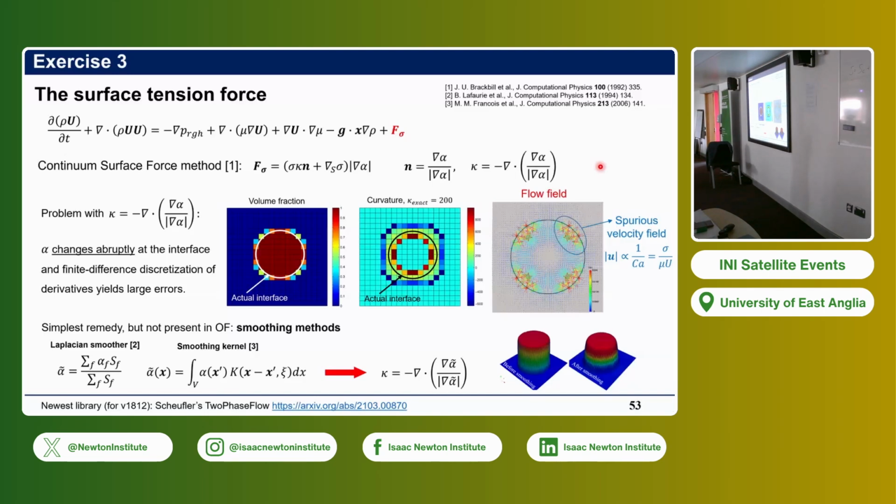Yeah, absolutely. Let's say in OpenFOAM, contact lines are naturally handled independently of the domain shape, independently of the mesh. But by default, in the VOF method, there is only a static contact angle. So it would not change over time. You cannot implement the effect of a moving contact line. But it's there, and actually, on GitHub, you can also find many libraries with dynamic contact angle. Actually, the two-phase flow library has the Cox-Voinov and all the possible formulations for dynamic contact angle. So this is a very powerful library to try out.